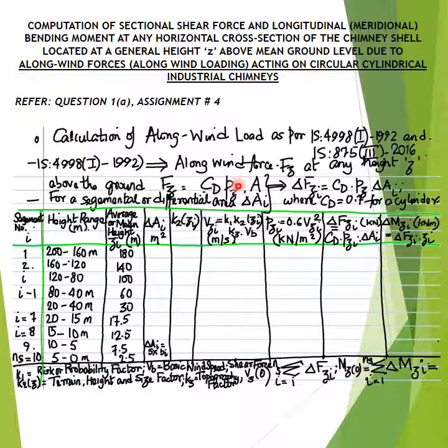which is a factor that accounts for cyclonic vulnerability of the region or site of construction, while the parameter VB, that is capital V subscript B, represents the basic wind speed given by the wind speed map of India, that is illustrated in figure 1 of IS 875 Part 3 2016 revision.